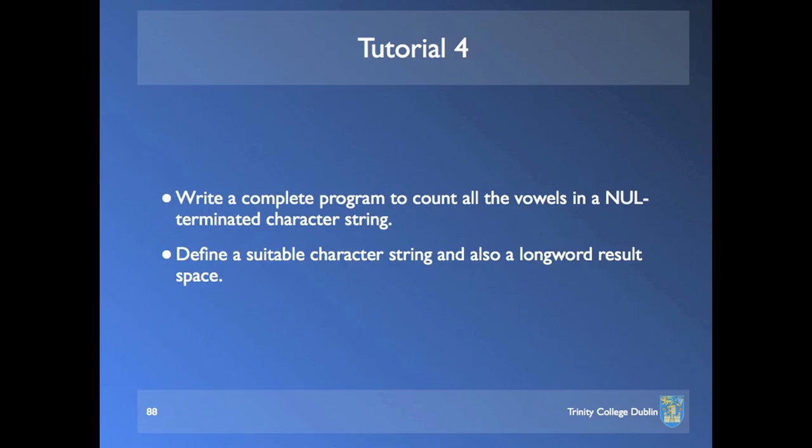Okay? And so that means that if all of these add up to the result, like we're talking about unsigned arithmetic, I can't figure out signed arithmetic at the moment in this connection, but if it's unsigned arithmetic, that means we're guaranteed that there'll never be overflow or carry out here. But that's by analysis, that's not by looking at it and thinking in terms of coding. That's by thinking about, if I may say, the theoretical side of it.